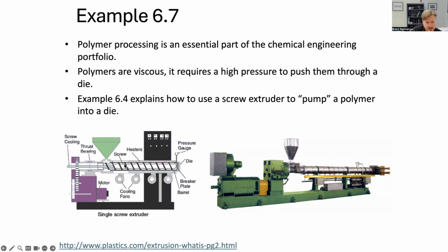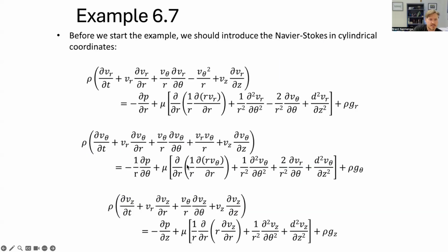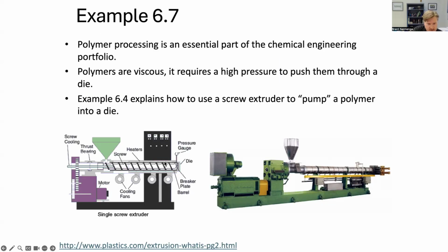You're going to be pushing the polymer through this outer pipe here, and then inside you're going to have a die right here that's where the polymer is going to be coming through. Right. So what is this? So basically you can imagine we're going to be doing a flow profile of a pipe, but then it has a core, another pipe. So it's just going to be the flow around the outside shell of the pipe that's between the center part and then the outside here. So clearly this is going to be easier to solve in cylindrical coordinates because it's basically a pipe.